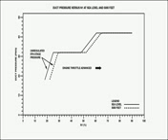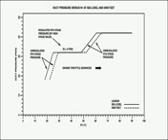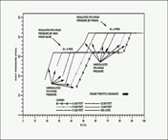There are also callouts that show the mode of operation the system should be in for each segment of those lines. This chart shows the bleed schedules for higher altitudes. Here's an example of how to use these charts. To make things easier to see, let's concentrate on the bleed schedule for 37,000 feet.